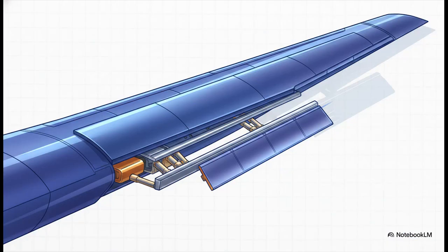For the test, definitely pay close attention to the Fowler flap. It's technically a specialized slotted flap, but with a major structural twist. Instead of just hinging downward, Fowler flaps slide backward on tracks. Remember this key phrase: Fowler flaps uniquely increase both the camber of the wing and the total wing area. At first, as they extend back, they increase lift dramatically without much of a drag penalty. It's only at the very end of their downward travel that they really start piling on the drag.